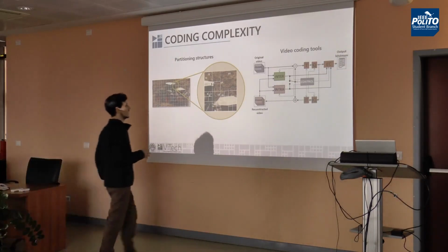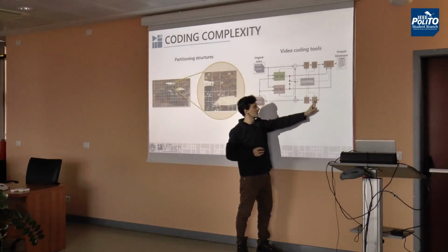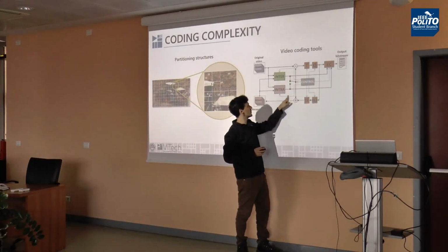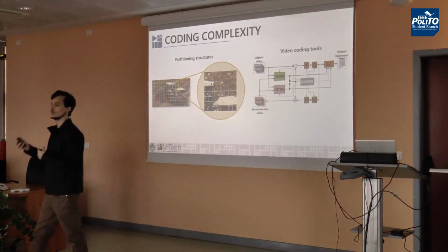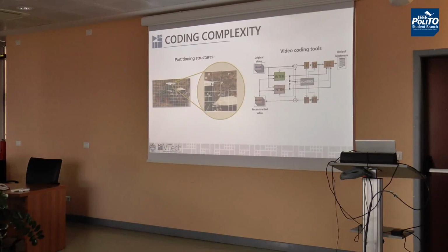Of course, you need a closed loop, inverse quantization, inverse transform, so the predictors can use it in a closed loop fashion. This is called a hybrid video encoder. It's hybrid because there is prediction, there is transform base, and there is also entropy encoding. So 3 styles, 3 ways to do the job, right? And we use all of them together to reach good numbers.